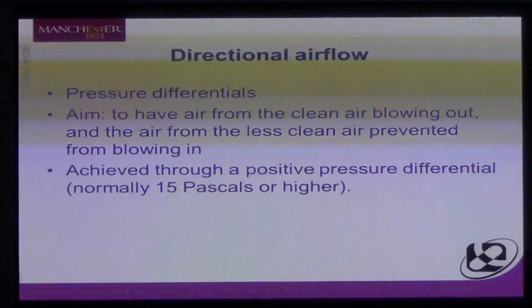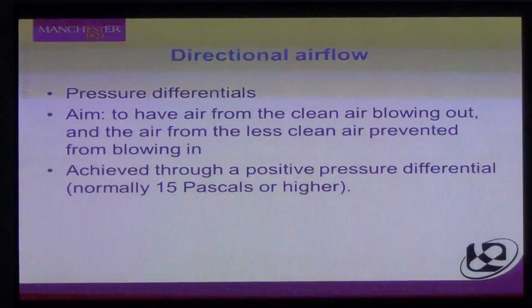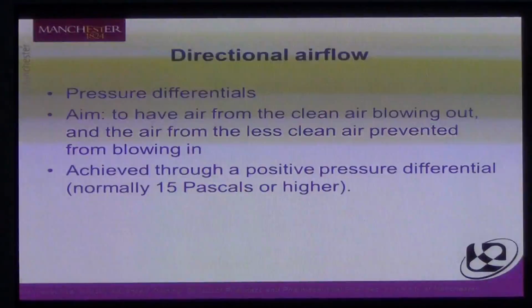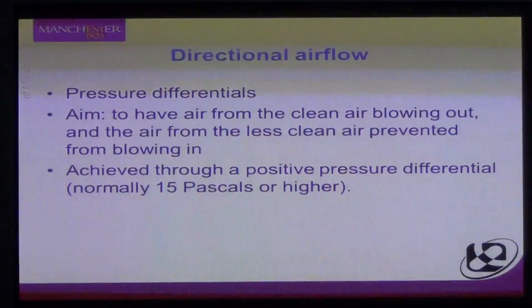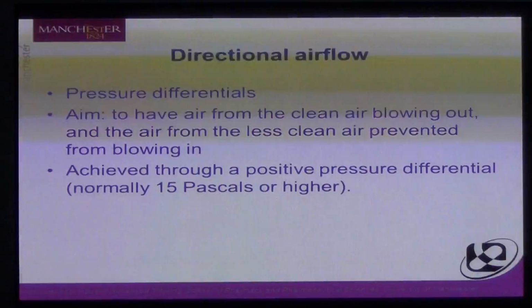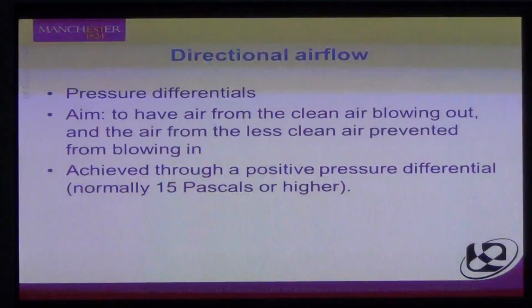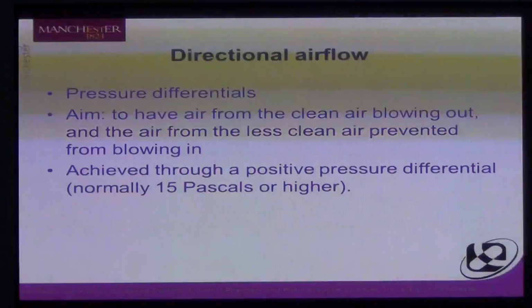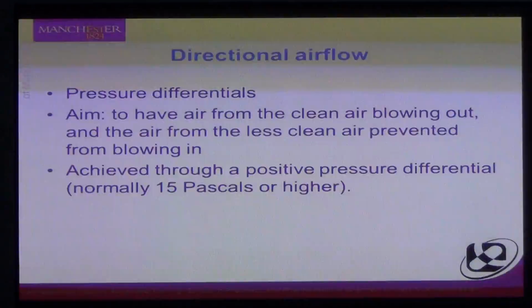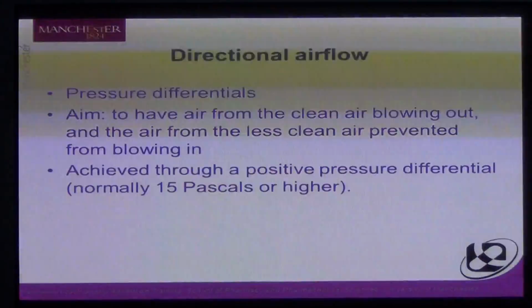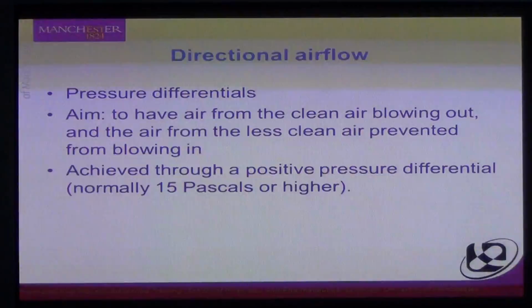This is created by having a pressure differential, and we measure pressure with the current SI unit of pascals, and normally areas are at least 15, often 20 pascals higher for the cleaner area compared to the less clean area. So these concepts may be a little difficult to take in if you're not used to clean rooms, but they are explained at length in the module.